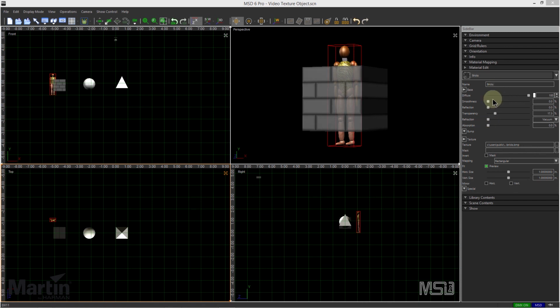Some of the settings here don't have any incidence on the look there until you do a static rendering. That will be the case for reflection, refraction, absorption. All of these settings, the result will only be seen once you do a static rendering. Just one here, we talked about self-illumination before in the environment tab. This is the setting here, so we can give light to an object. So an object will basically be brighter. So you can use this setting here to set the self-illumination.